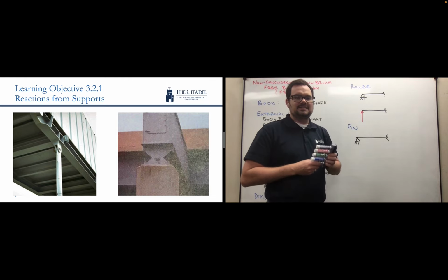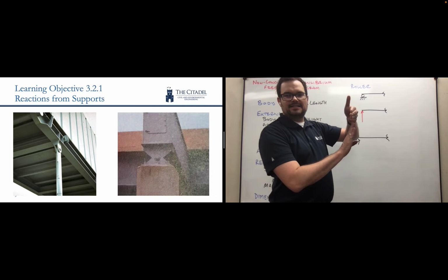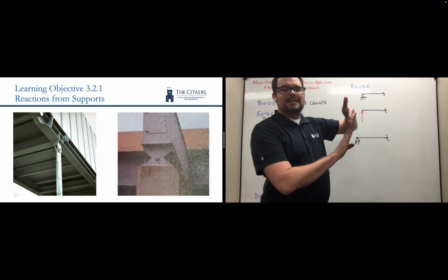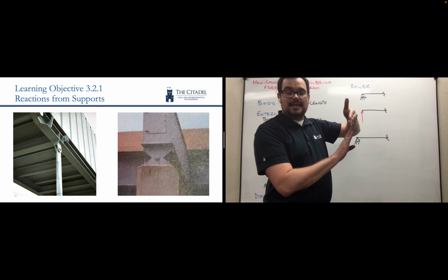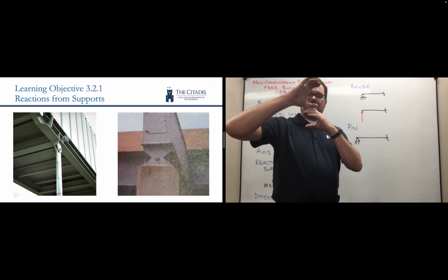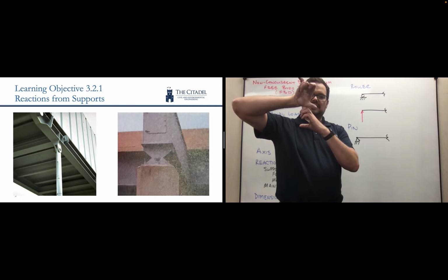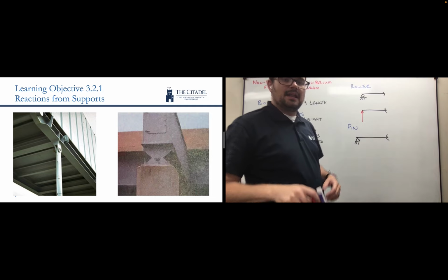And so if we look at this on the left diagram, we have a beam. It's pinned in place on a fixed vertical column. And so we're going to ask those questions again. Can it translate? Can it rotate about particular axes? Same thing in the right picture. They've come down and it's pinned here, and we're kind of looking along this beam that's being resisted in this 2D view.